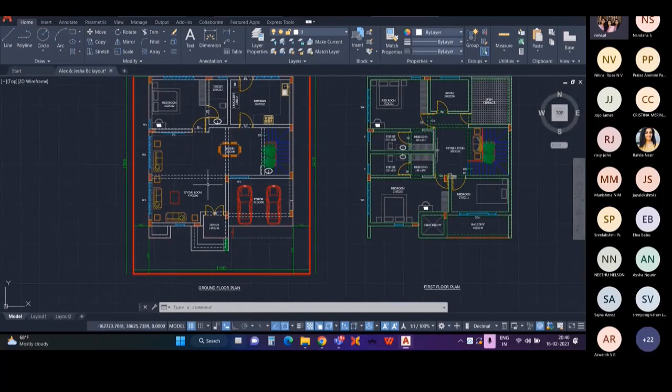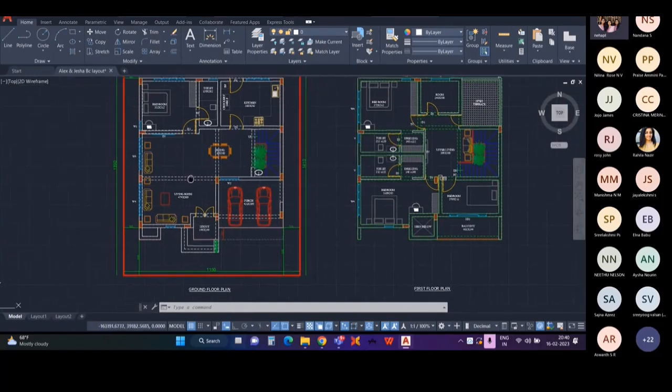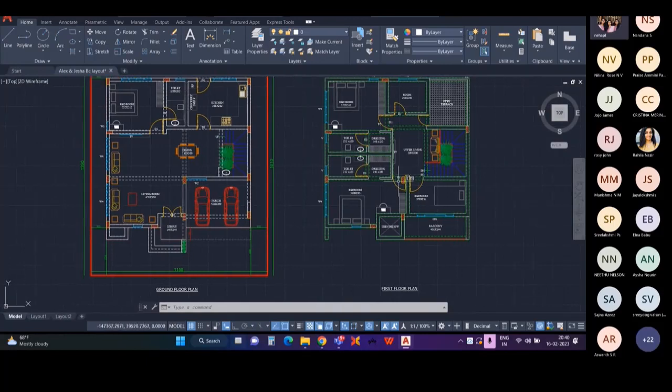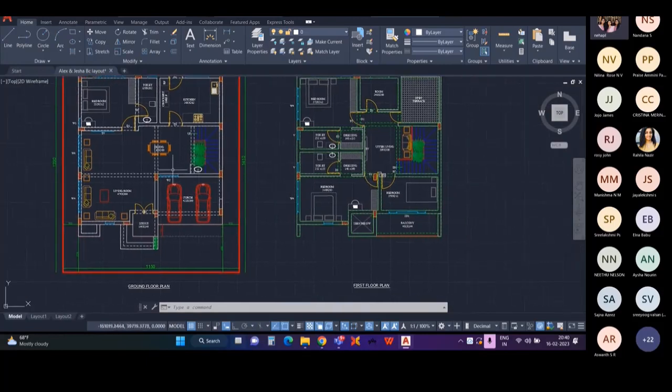If we shift it to the left side, it will be coming at the living room. So when we enter through this main door, we can see a column at this living room. If we shift this column towards the right, it will be coming at the parking area. So we cannot provide a column here. Let's try to find another way so that we can balance, so we can reduce the 9-meter distance.